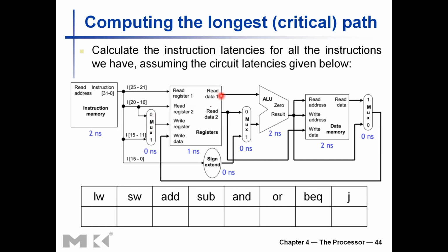After the register file we have the ALU, and between those we have the multiplexer and the sign extension unit on the immediate operand if there is an immediate operand, and at the end we have the data memory where if this is a load instruction we read, and if this is a store word instruction we write. And if it is a load word instruction, we need to decide whether to take the word read from the memory, or the ALU result, to write to the register file. So we have another multiplexer.